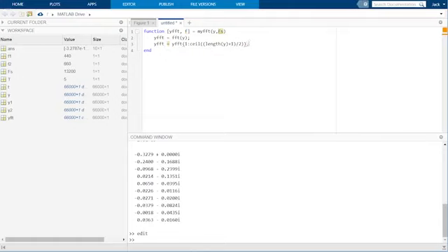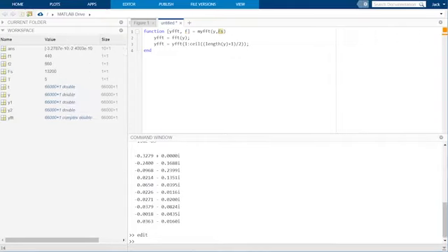The remaining part of the FFT that we throw away corresponds to what are called negative frequency components that we would need if we wanted to represent complex valued signals. Next, we can also compute the frequencies that each entry in the IFFT corresponds to. This is not something MATLAB gives us by default, but knowing these frequency numbers is useful.